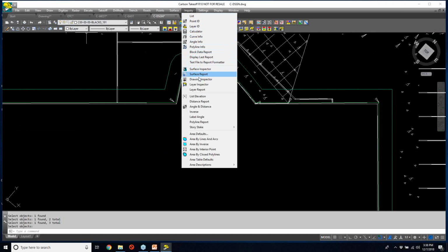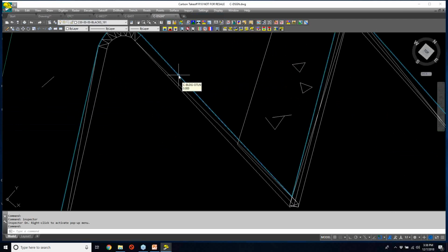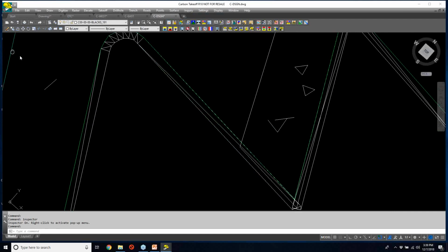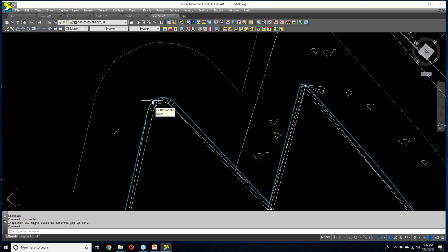If I go back to my drawing inspector and take a look at this green polyline, right now it's on the C building outline layer and it's down at elevation 0. Also, the green 5-foot offset is on a C building overhead layer, and it's currently at the desired elevation. So when we go to make a surface model, we're going to utilize the elevation here, but we will perform the subgrade adjustments accounting for, say, 8 inches of concrete slab, and maybe the aggregate base underneath for this building shape.